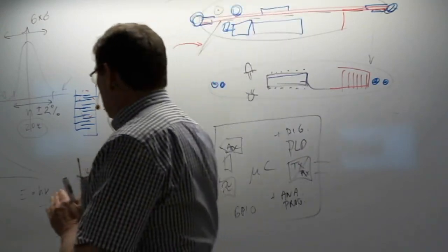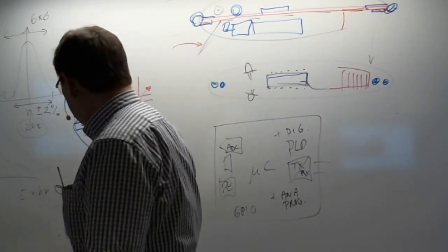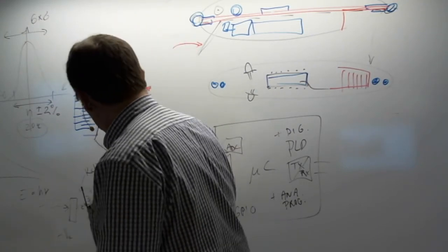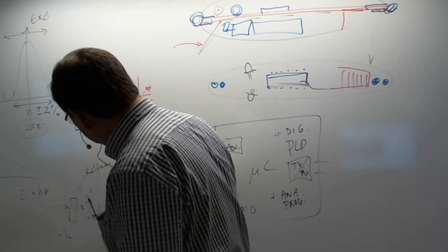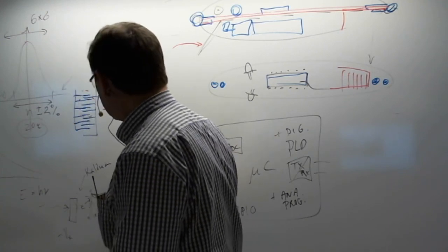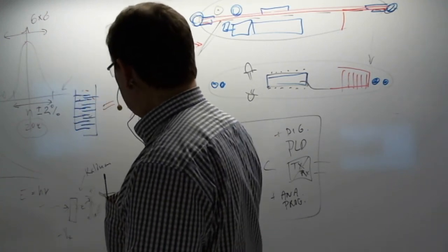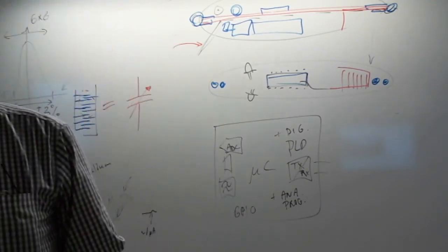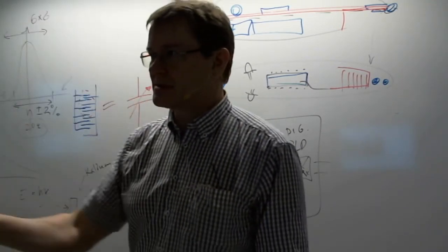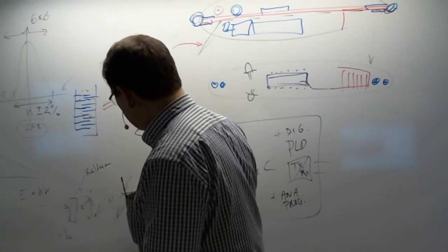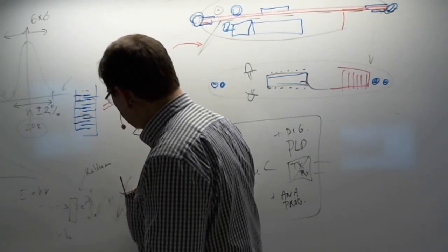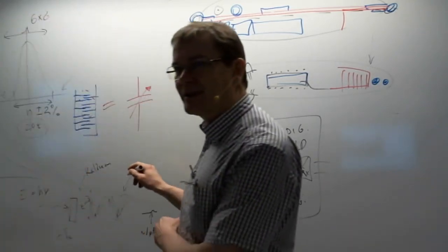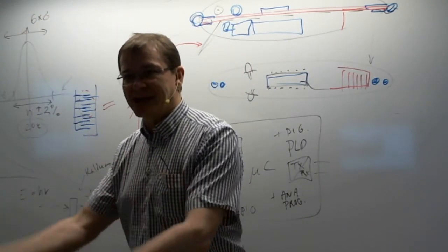Okay, so this one actually has a tendency of saturating, meaning that, well, physically the later dynodes cannot give enough electrons anymore, and basically some of that, when you have higher energy here, it starts to just generate heat, and you start to heat the dynode, and it doesn't release that many electrons anymore.